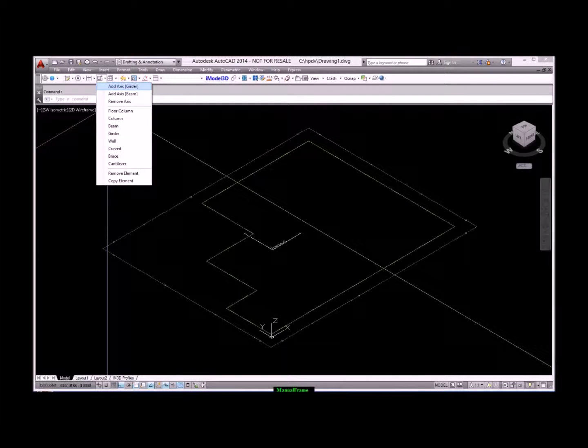The Use Frame Axis checkbox specifies whether you already drew the floor axes and you want to use them as the frame base axes, which will be discussed later. If this checkbox is left unchecked, that means you want to specify the frame base axes manually. After you click the OK button, you will be asked to select the building boundary and the axes if you checked the option mentioned above. Floor height and slab thickness are in centimeters for metric and in feet in imperial units.